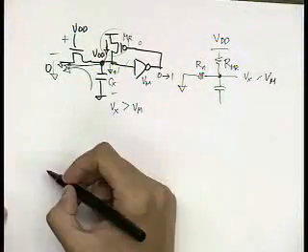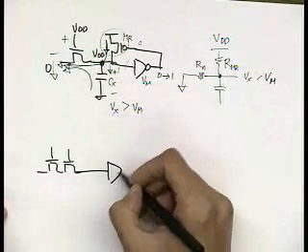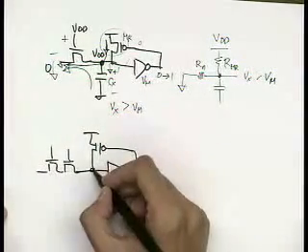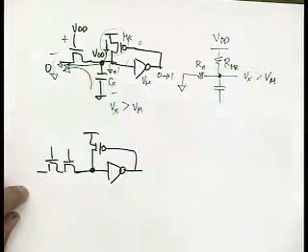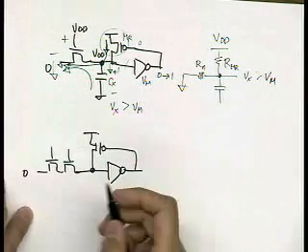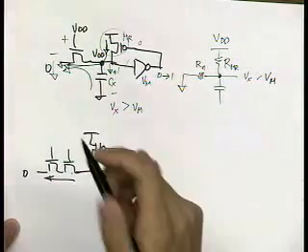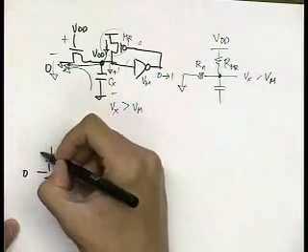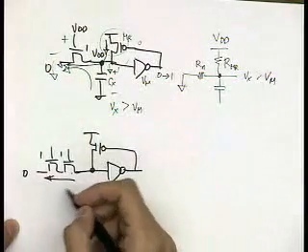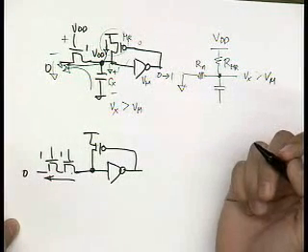For that multiplexer, you could have 2 transistors driving this inverter, now with a level restorer. Okay, so if I'm putting a 0 here, then the current here, if this were the same size as this, then the current here would be less. Okay, it means that I have to make the restorer weaker.